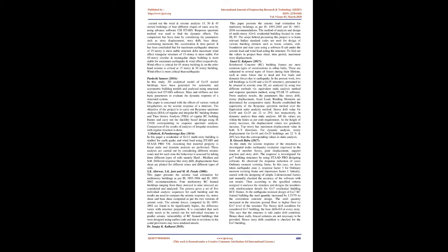Parameter K. This coefficient represents the inelastic, plastic behavior of facilities when exposed to seismic loads, and its value decreases as the building compliance increases, and its value is taken from the following table: characteristics of the structural system, K. High water tanks and the like, carried on a group of columns not less than 4, and adequately connected horizontally in both directions, 2.5. Special establishments, chimneys, minarets, television towers, cooling towers.